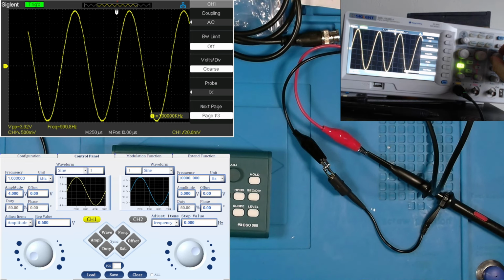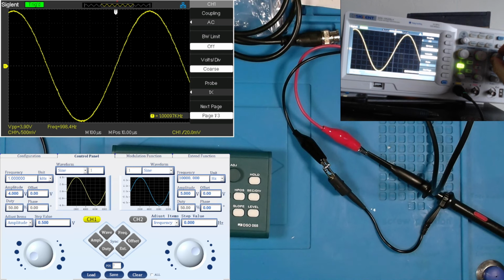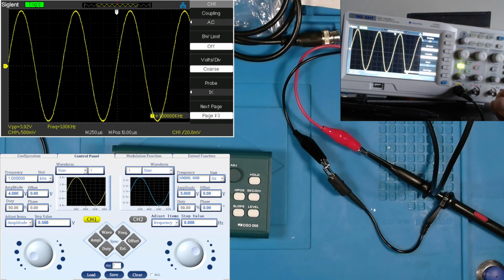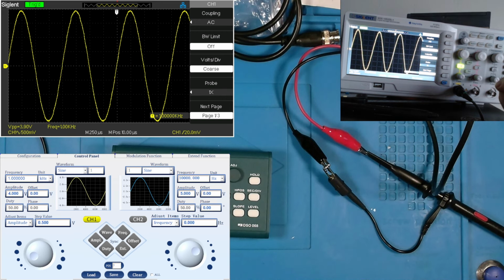So you could potentially have, with a multimeter, a 4-volt peak-to-peak measurement, or as we also learned, you could measure a 1 kHz tone with a multimeter, but the frequency could actually look pretty terrible. So the oscilloscope gives me the ability to actually see the waveform and a little bit more in-depth diagnosis on how it looks.